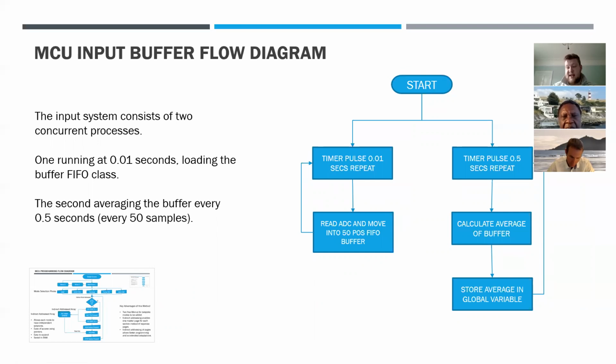So we're always trying to get a consistent average. PLCs don't require a quick change in signal, so this can be quite a slow process, thus every 0.5 seconds. It doesn't need to be every 10 milliseconds, because the changes with these switches are very, very slow.